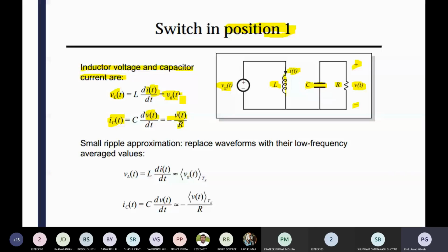If you plot the dynamics, initially it will be oscillating. If you see the step response, the time response, the phase portrait is not your time response. Time is there, one axis is time, but you should calculate it in the back of your mind. In a phase portrait, one axis is one state variable and the other axis is another state variable. But the step response is totally time domain analysis. On the x-axis you have the time axis, and on the y-axis one of your state variables.